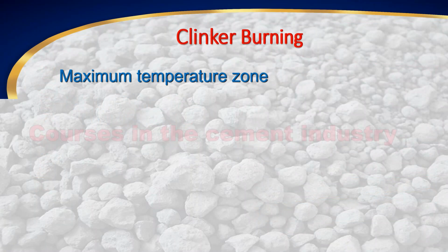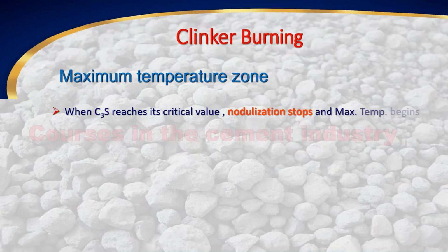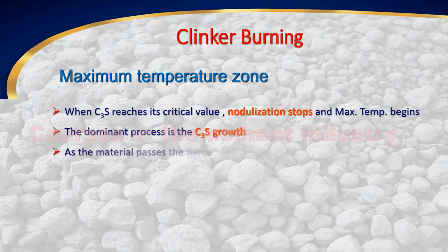Maximum temperature zone. 1. When C3S reaches its critical value, nodulization stops, and maximum temperature begins. 2. The dominant process is the C3S growth. 3. As the material passes the flame, its temperature decreases, and phases solidify.